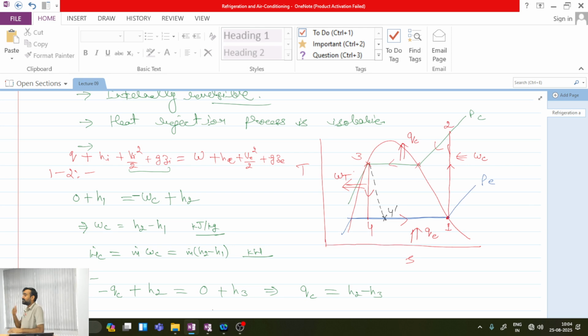And you know that whenever you practically install the system, the difference of enthalpy is not the actual amount of work we get. In addition, the shaft will be rotating, it is put on some bearings, and there can be some gear arrangement. All these transmission elements lead to certain losses. If your amount of work is very small, it may not be sufficient even to overcome the losses, and ultimately you will get nothing but zero output from this turbine. So that is the reason.